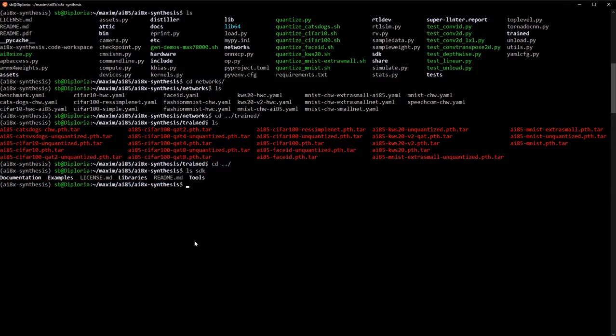This pre-generated content allows you to start at just about any point from training to synthesis to C code and immediately generate output. However, it's important to understand that by running scripts like GenDemos or the quantize scripts or the training scripts back in the training repo, you will be overriding pre-generated content. Working from the demo models and related scripts and resulting C projects is a good place to start, but you'll quickly want to start branching off into a customized workflow specific to your project.